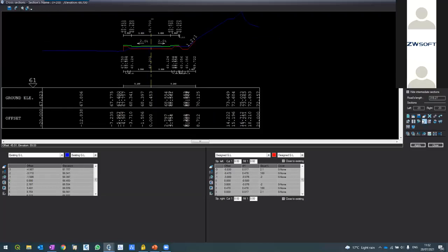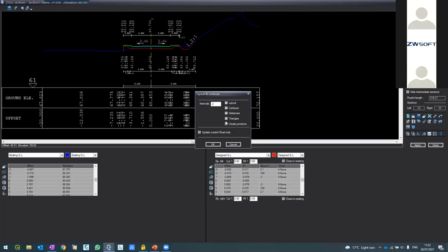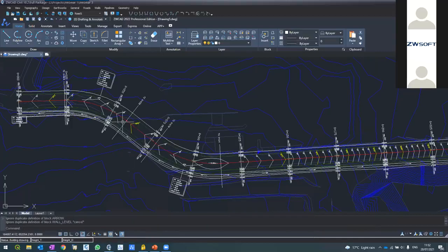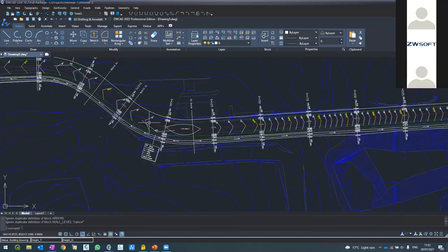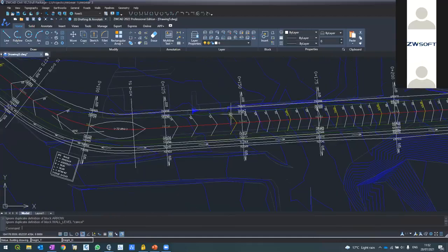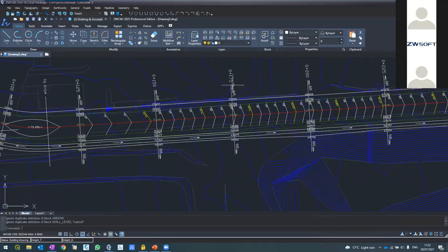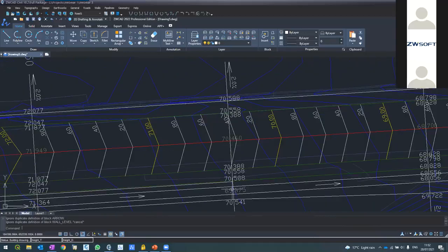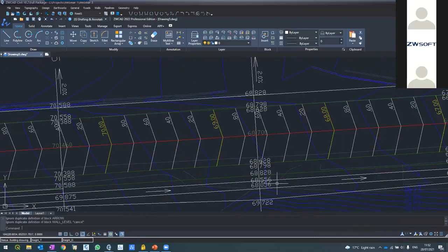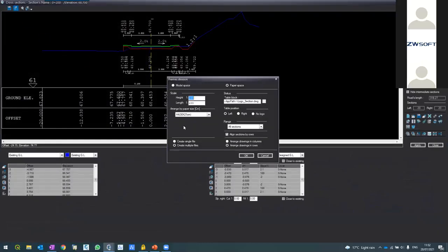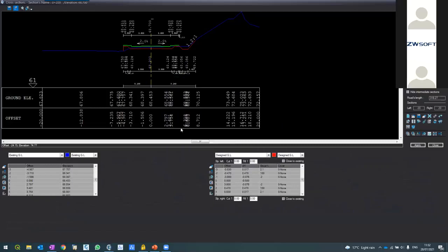I have the cross sections. I can see the corridor if I want. Okay, so all the data, the labels of the corridors, including the contour line, the side ditch with the flow direction is here. We have the elevation of the levels in the roads, also in the ditch. Everything is here. I can also tell the software, create sheets of A0 of my cross sections.